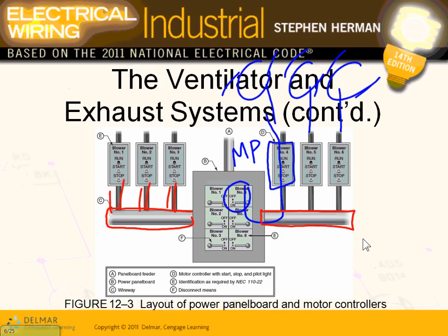You have two ways of bringing the feeders out from this panel, Chris. You can bring the feeders out in individual conduits, where every individual conduit comes directly to the panel. Or what they did is they have a gutter extending the panel, and from the gutter they tap in to feed all this equipment.